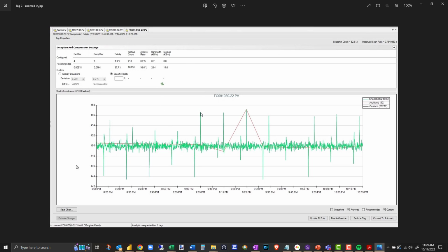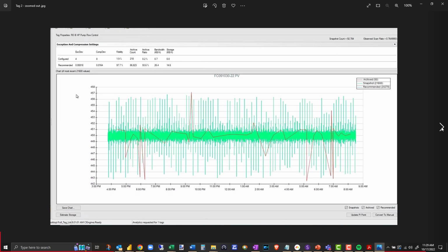One of the other things I see is, I think you have some instrumentation issues. All these little blips, I think you have some kind of weird instrumentation problem, or you got noise in the system, or something like a motor starting or stopping. So this is it zoomed out. This is what it looks like overall over a long period of time. That's like 5 hours. The thing is the red line does not look like the green line at all, right?